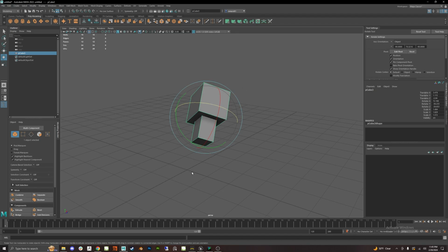I.e., it's going to think that it should be over here when it's not, and it might cause a scale issue where it might send this thing, which is called the gizmo, and put it here instead of right here. It could crush the object, it could misconform the object, it could do all kinds of things. We don't want that. What we want to do is delete the transforms so we can reset all of these back to 0, while keeping this object where we placed it.